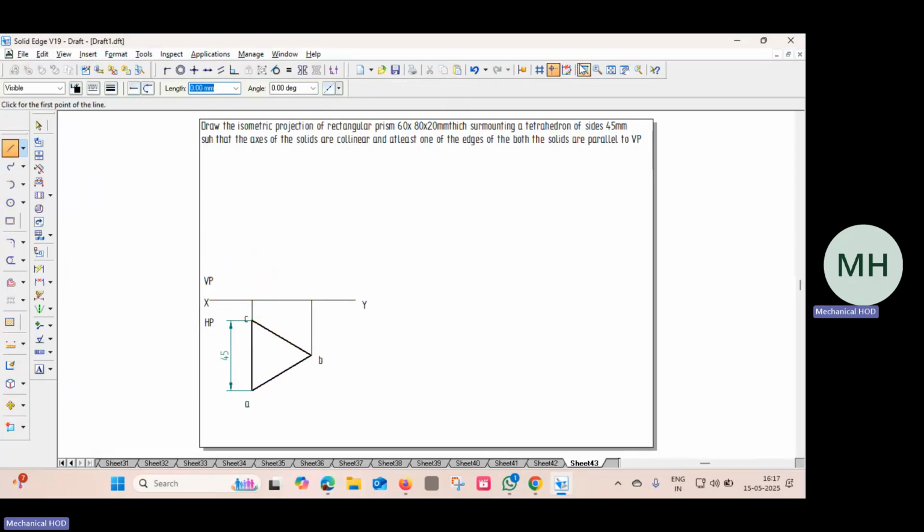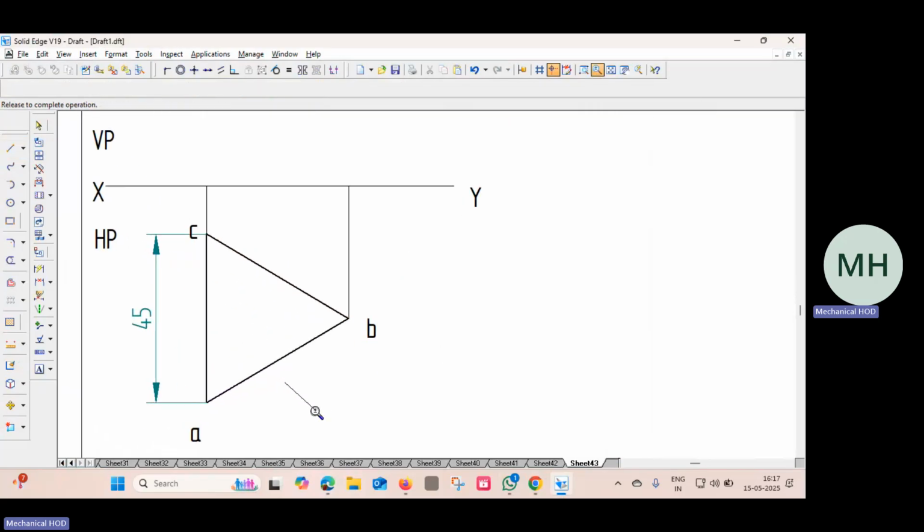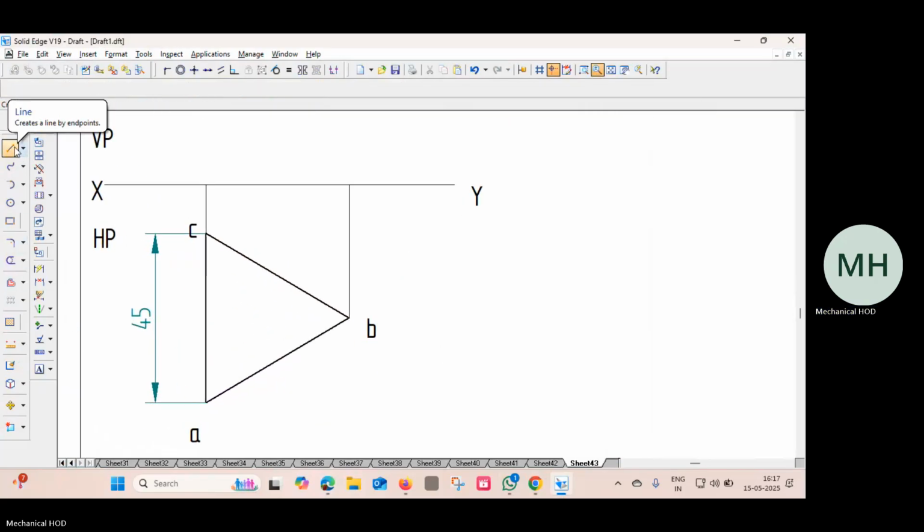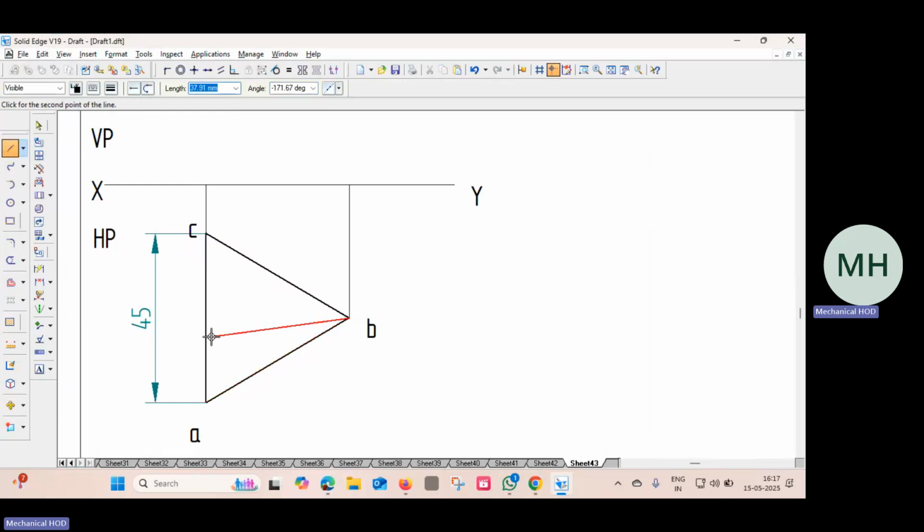Here we have to find out the center of the triangle. How to find the center of the triangle? By joining the medians. A median is a line connecting a corner of the triangle to the center of the opposite edge. Scroll on AC and find the midpoint symbol; you can see the symbol adjacent to the cursor. Once you get it, left click. Similarly, start from A, scroll on BC, reach the midpoint, and click. Once more, starting from C, scroll on AB, get the midpoint symbol and click. So this is the center of the triangle.